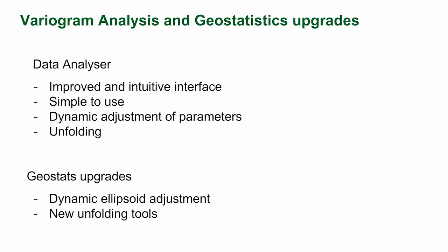Thanks, Steve. While Vulcan has always included the ability to analyze data and create variograms, the enhancements in version 10 really add ease of use to the package. Data analysis now has a custom interface, which is intuitive and easy to use. Making adjustments to variogram parameters is now dynamic, with settings such as lag size, range, and orientation now adjustable on the fly. Today I'm going to run through the basic functionality of how to get data into the data analyzer, run filters, create variograms, and produce outputs suitable for grade estimation in your final reports.